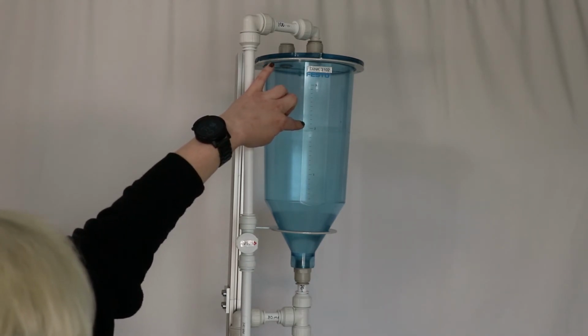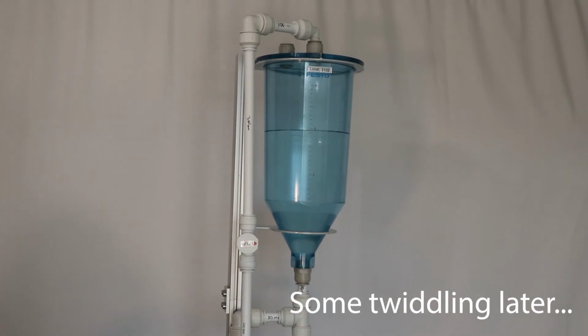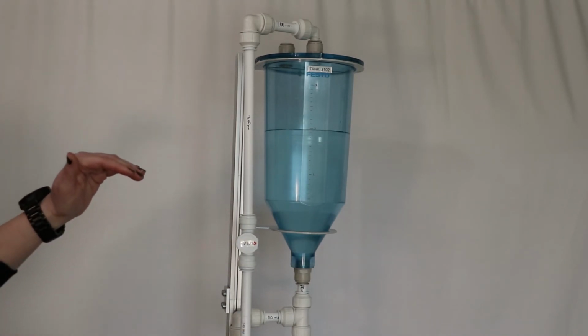I do have a little bit of a steady state error, and I am climbing a very little bit, so I would have to adjust this. I can't adjust it in smaller increments. About 12.6, and that's staying pretty stable. So we're going to say that currently my steady state value with this withdrawal rate is 12.6 volts on this motor. And my system would eventually come to that, and it would eventually balance out at that point. So we call this steady state.